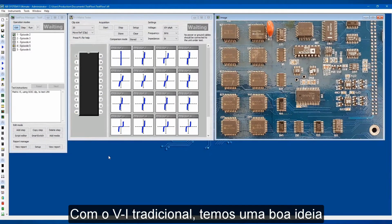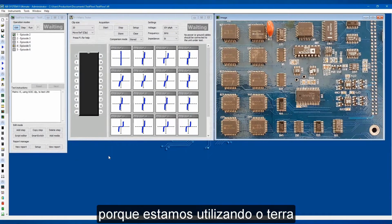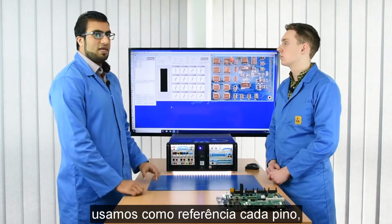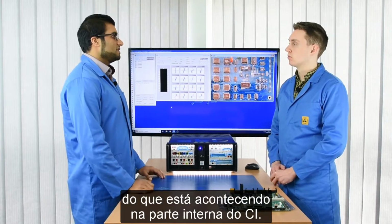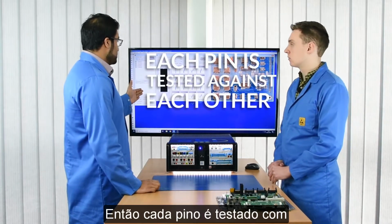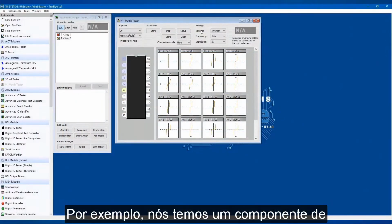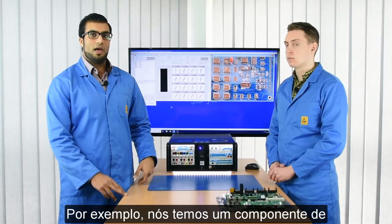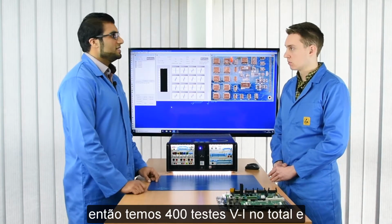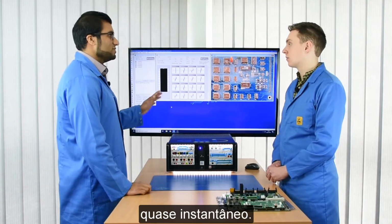With the traditional VI, it gives you more of an idea of what is going on around the device, as we are using the ground as a reference. But since each pin is being used as a reference with the matrix VI, it gives you a good understanding of what is going on within the device itself. So each pin is being tested against each other, pin 1 against pin 1, pin 1 against pin 2, and so on. For example, let's say we have a 20-pin device, 20 lots of 20 tests, so 400 in total. And as demonstrated, all those tests happen almost instantly.